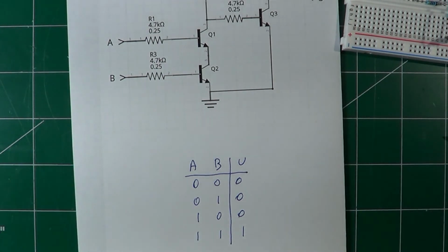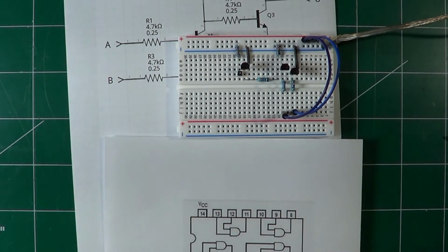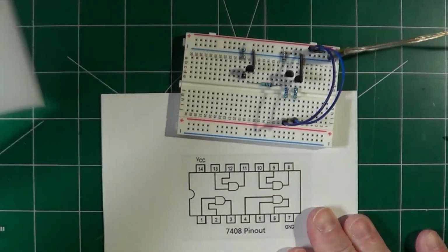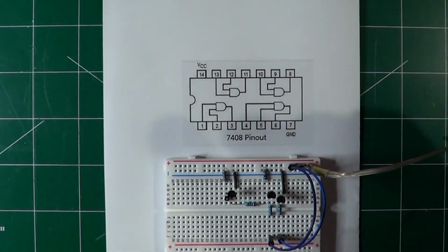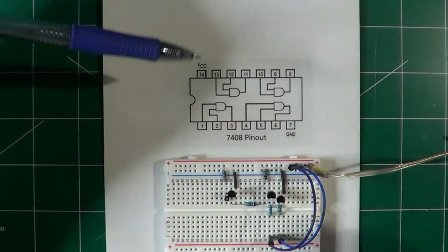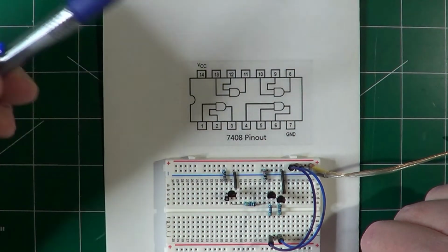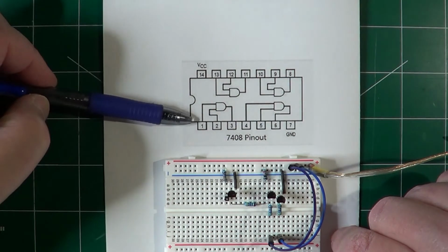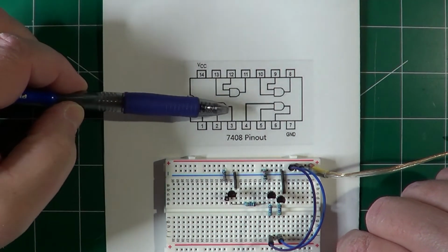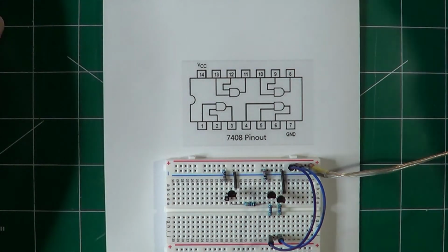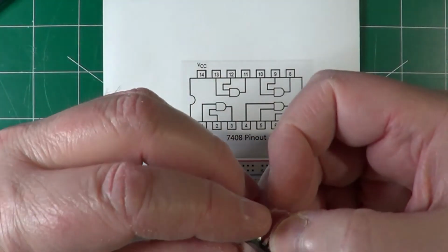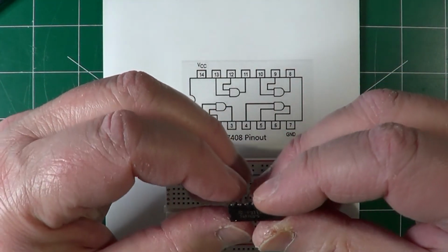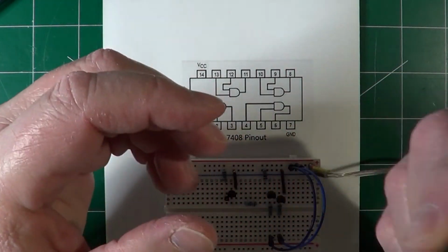And again, we can use an integrated circuit to make the AND ports. And this is how the IC I decided to use looks like. Once again, pins 14 and 7 are used to power up the module, and the pinout is practically the same as the IC with the NAND gates, but this time these are AND gates. It is a through-the-hole dual in-line configuration with a total of 14 pins.